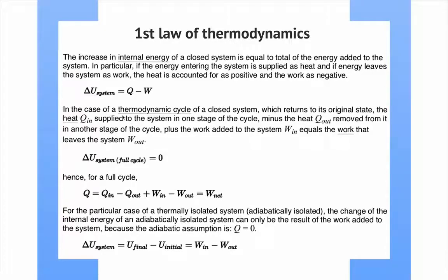So in the case of a thermodynamic cycle of a closed system, which returns to its original state, just like the internal combustion engine comes back to its original state, so it's a cycle, the heat Q in supplied to the system in one stage of the cycle minus the heat Q out removed from it in another stage of the cycle plus the work added to the system W in equals the work that leaves the system W out. It's basically restating this equation.